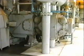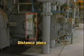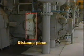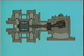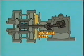Between the crosshead bed section and the cylinder is the distance piece. This is where you'll find the wiper rings and pressure packing. The distance piece prevents any process gas from leaking into the crankcase and provides a way to vent any leaking gas away from the compressor.